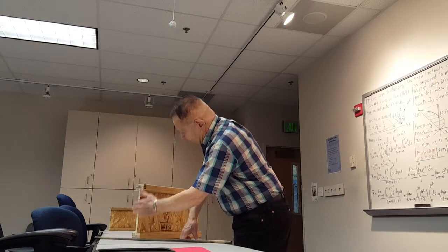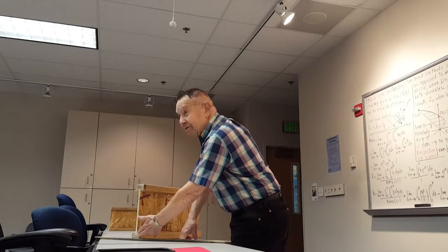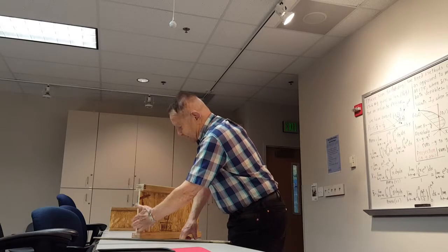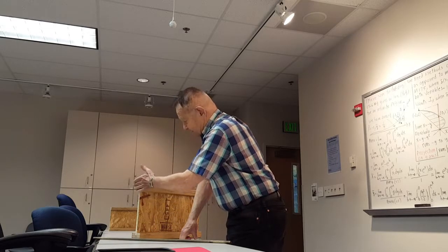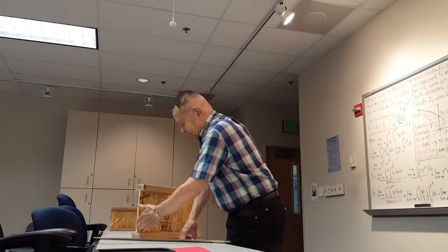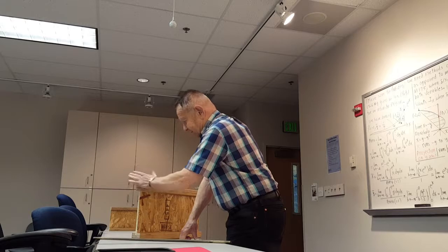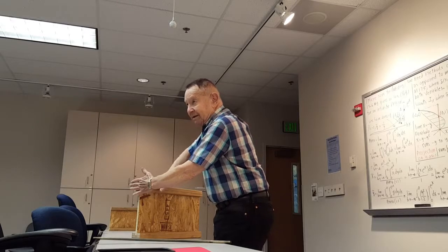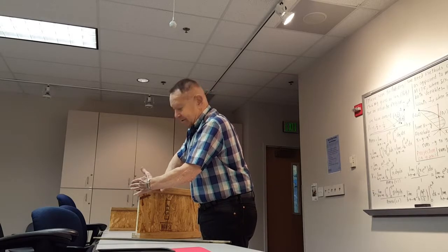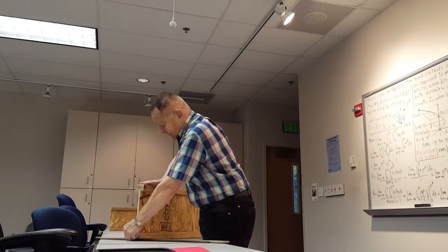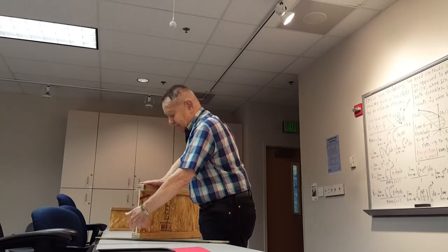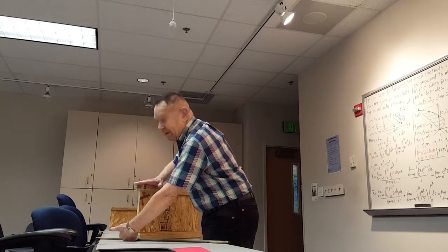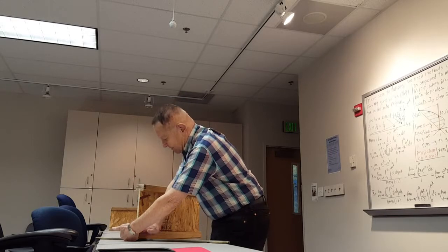Notice if you have a thing like this, you have to break it into three problems because you've got a rectangular cross-section down here, then this rectangle, and then another cross-section up here. But the contribution to the integral from this cross-section is by far the largest because you're using the squared distance as a multiplier, and the squared distance between my hands is certainly a lot more up here than down here.